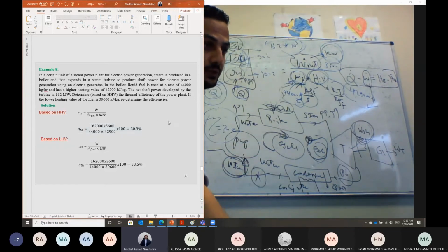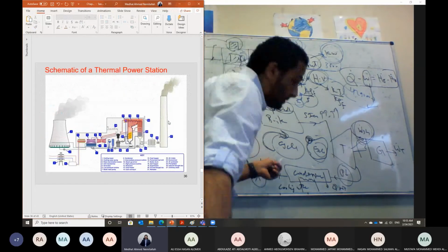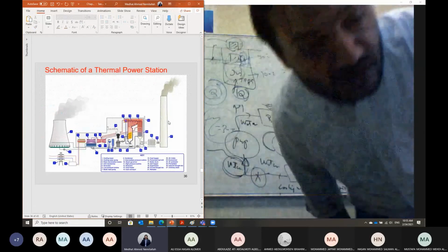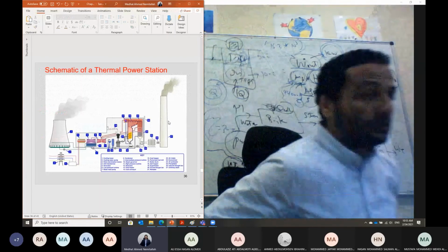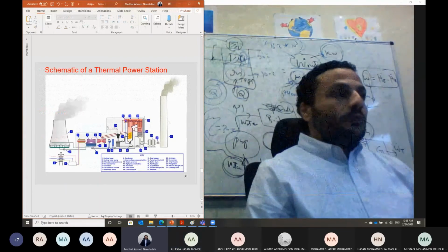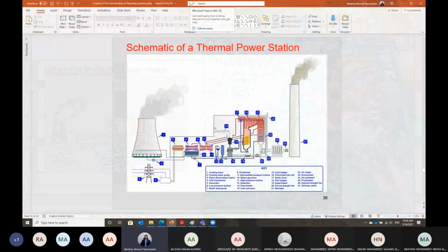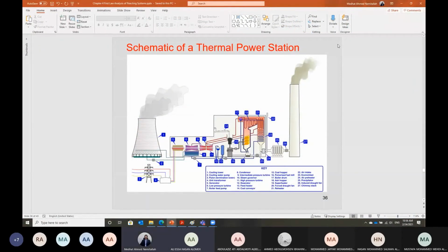And this is the concept of operation related to the cycle, the heat engine. Any heat engine, to generate continuous work, has to work on a cycle. This is the thermal efficiency, right? Not the overall efficiency, because we didn't consider the pump. We didn't consider the electric generator. Yes, this is not the overall one. This is the thermal efficiency of the cycle.